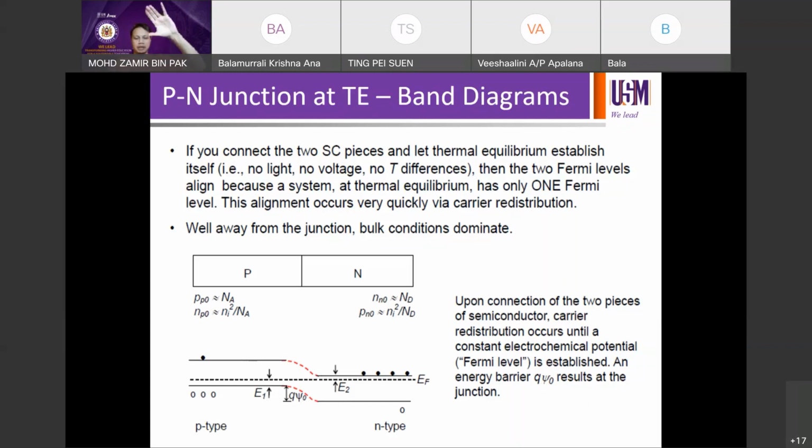So when you form this barrier at thermal equilibrium, the carriers from both sides will see a wall in front of them, physically, just to make things easier. They will see a high barrier, like a wall, that will stop them from diffusing to the neighboring region, and this will stop further diffusion. Meaning they get blocked. Majority electrons will be blocked on the n side. Majority carrier holes can only stay on the p side because of the barrier in between, and that's called the energy barrier.